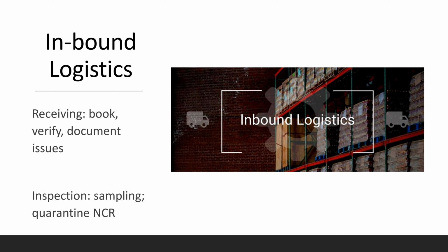Let's talk about inspection. I apply the right level of incoming inspection. For fully approved suppliers on stable parts, I may accept on certificates with spot checks. For new or risky parts, I follow an agreed sampling plan and verify critical dimensions or attributes. I record results, lot numbers, and expiry dates. Non-conforming material goes to a clearly marked quarantine area with a hold ticket, and I raise a non-conformance for disposition.